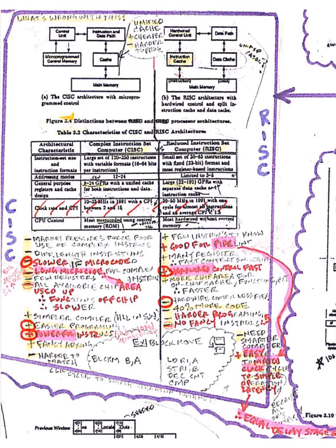In the control unit, in the CPUs, the cores, the sequencer that executes the machine instruction cycle, the pipeline stages, pulls all the strings in the data path. That can be either micro-coded or hardwired. Micro-coding means it's programmed separately. It has its own little sequencer. Each instruction has its own little sequence programmed, and there's a finite state machine just for doing that.